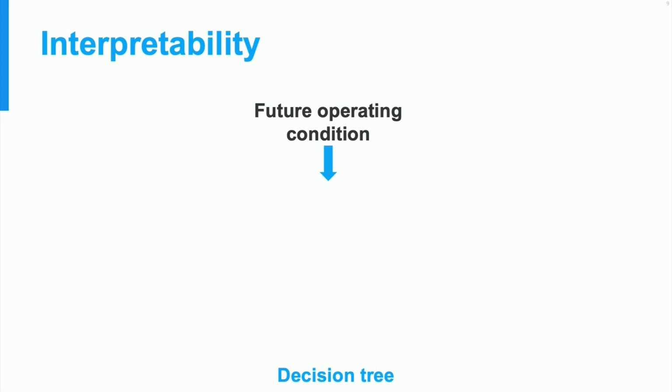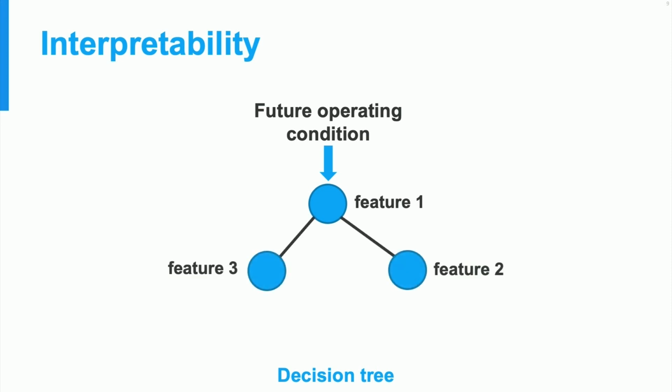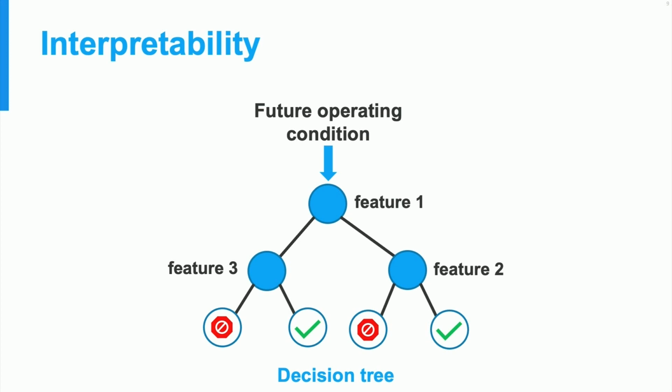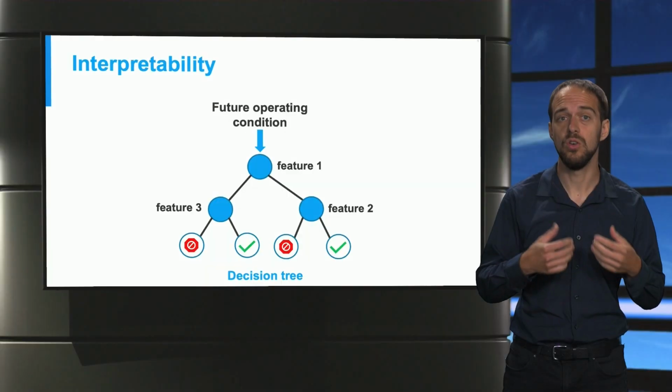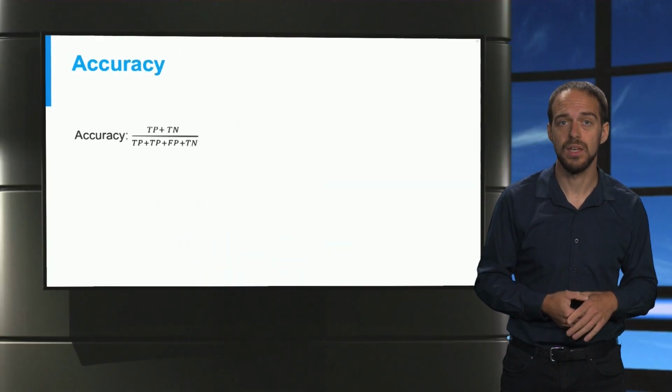An example of an interpretable model is a decision tree. There we have the decision tree structure, where the power system operating condition is going through the decision tree structure. The decision tree structure consists of split nodes that determine if the path is followed to the left or right, depending on a single threshold. Finally, the operating condition ends up in one of the leaf nodes, and a label for security or insecurity can be assigned. The ending leaf nodes are representing either secure or insecure operating conditions.